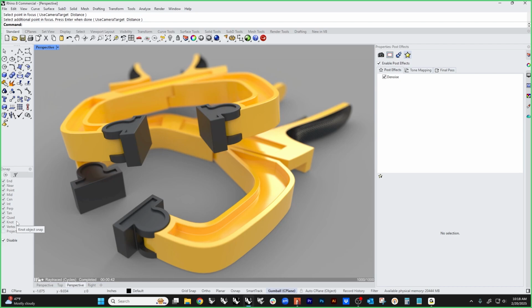Things to keep in mind: in our case, we forced the softening and it made some messy little edges here and there. If it's got messy edges in the render mesh, it'll have messy edges in the actual mesh that you extract.